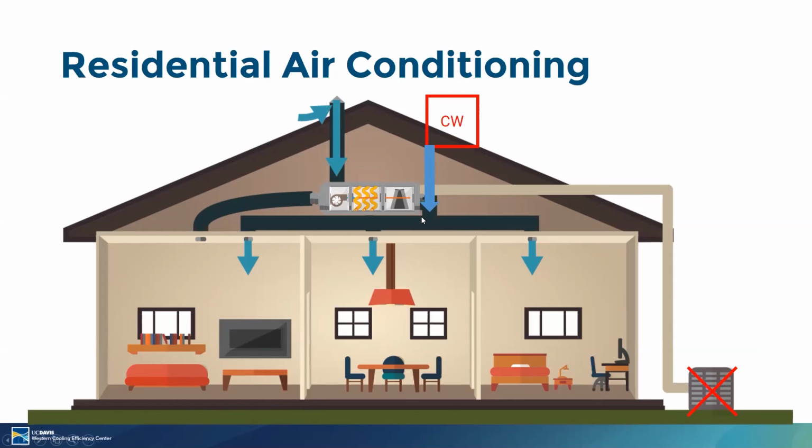What you have to think about when you do this is that the supply airflow for the Climate Wizard is greater than you would expect for a typical air handler. So we're going to have greater resistance in this duct system, and you'd somehow need a damper to swap back and forth between these two systems.